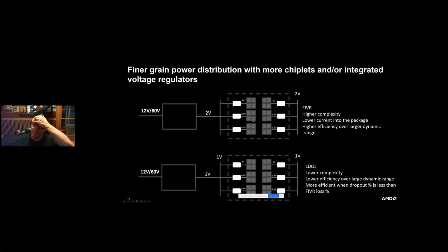And at least in the publications, I'm not aware of anyone other than Intel already having that in products, right? At least from the publications. Now, there are other ways to do this split with simple LDOs. LDOs are like impedance dividers. They are inefficient, right? Unless your input voltage and output voltage are very, very close. So you're not doing 2 to 1. You're essentially doing 1 to 1, or 1 to 0.8, or 1 to 0.9.